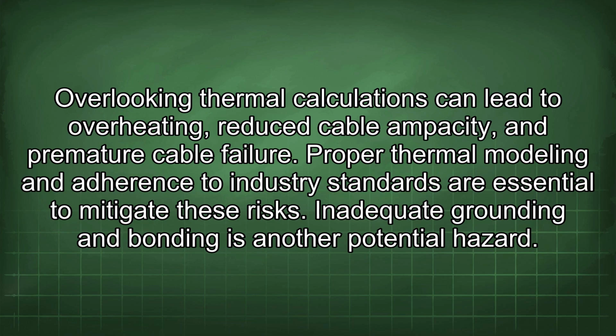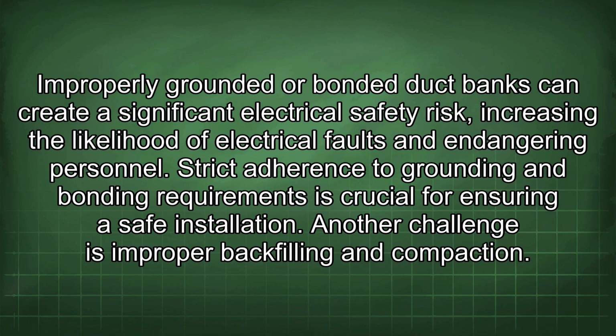Inadequate grounding and bonding is another potential hazard. Improperly grounded or bonded duct banks can create a significant electrical safety risk, increasing the likelihood of electrical faults and endangering personnel. Strict adherence to grounding and bonding requirements is crucial for ensuring a safe installation.